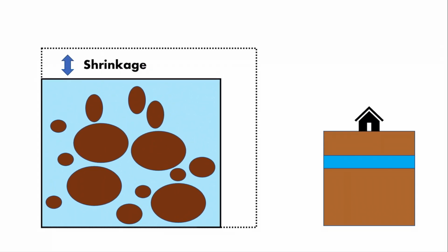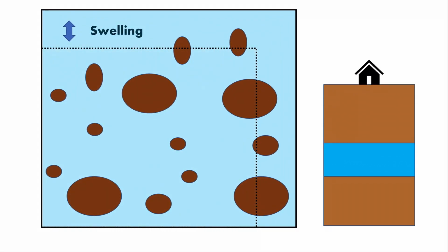Due to silty clay's property, London clay has much void water, which causes volume change of the soil. When a persistent water deficit develops as a result of leaks from water supply pipes or drains, subsidence of the building can occur due to shrinkage of the soil. When the persistent water deficit dissipates or void water is increased by heavy rain, heave of the building can occur due to swelling of the soil.